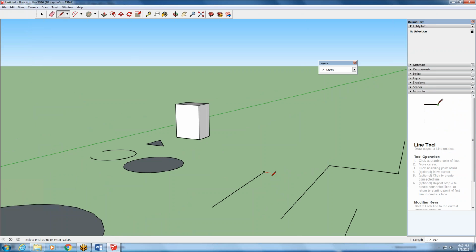Notice when I typed, it's different than AutoCAD, where we're real specific and we use the 2 dash and whatever when we're doing feet and inches. It doesn't do that. As you're drawing and you get into feet, it puts the inches right next to the 1 foot as opposed to separating them with the dash. If you want it to draw accurately, you need to set it up that way.